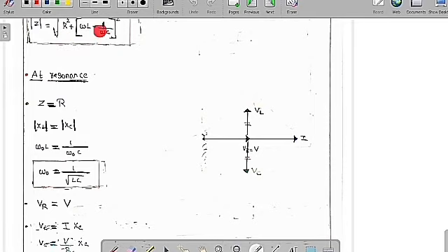So therefore it indicates that XL is equal to XC. Then only we are going to get this part as 0. So omega naught L is equal to 1 by omega naught C at one particular frequency, which is omega naught. With simplification, we are going to get omega naught is equal to 1 by under root of LC. Means at this angular frequency only we are going to get the inductive part equal to the capacitive part, and then the circuit is purely resistive. That we are going to call the resonant frequency, omega naught.